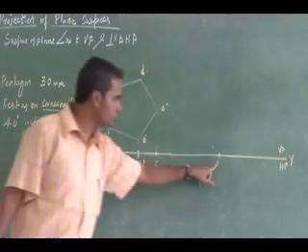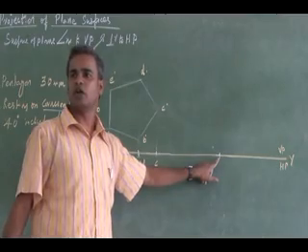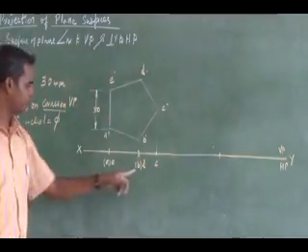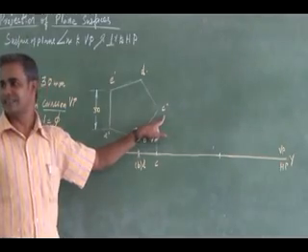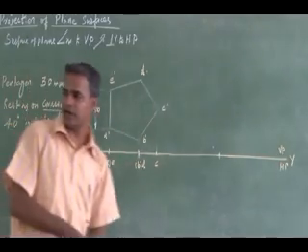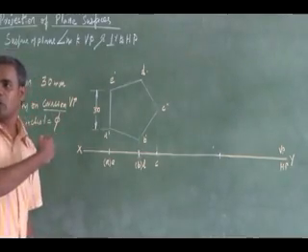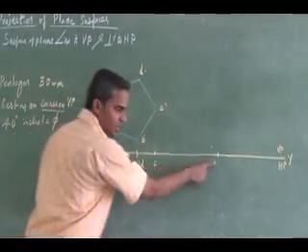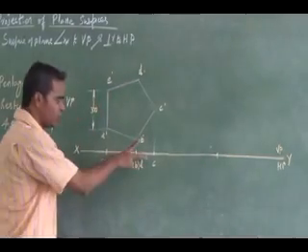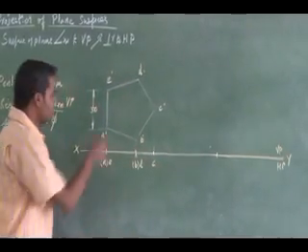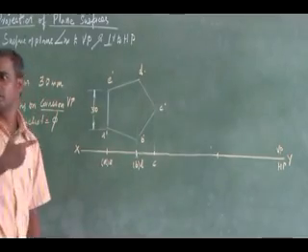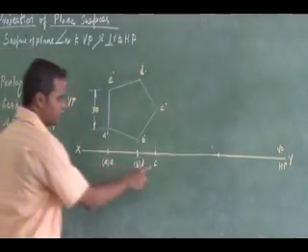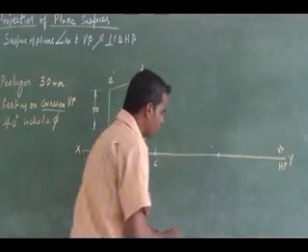The corner has to be marked on the reference line. So which is the corner I have here? I have C. The corner is C, and I have to mark that C. It depends upon the problem. If it is resting with an edge, I have to keep AE here, and then redraw and reproduce this top view. Here, since it is resting with the corner, it is an important one, you should not make a mistake. So here it is resting with the corner, and I have to mark the C.